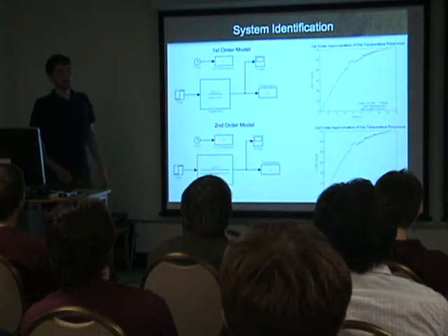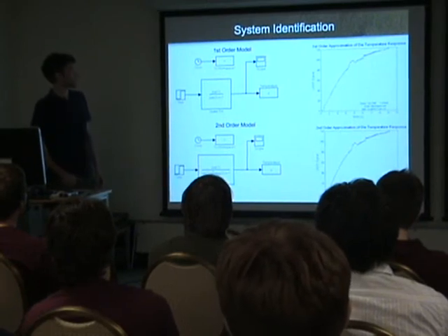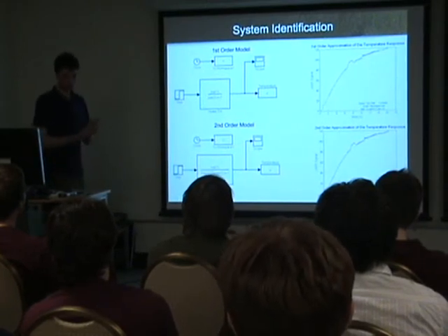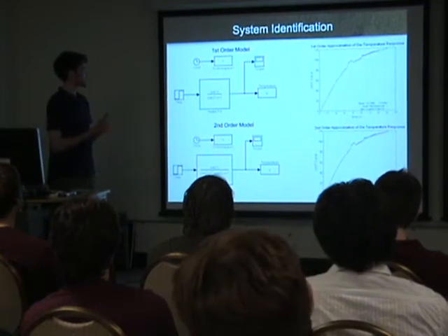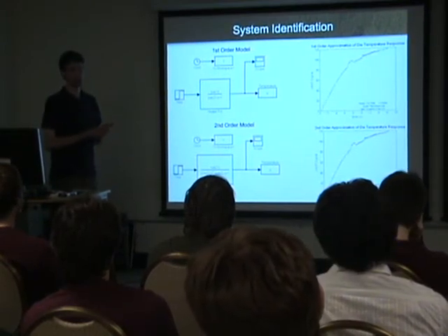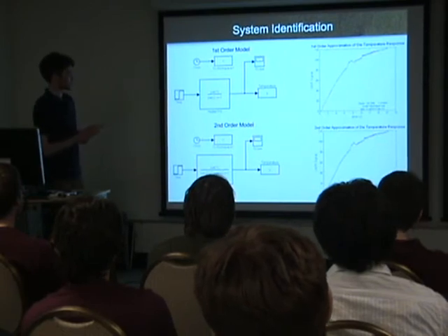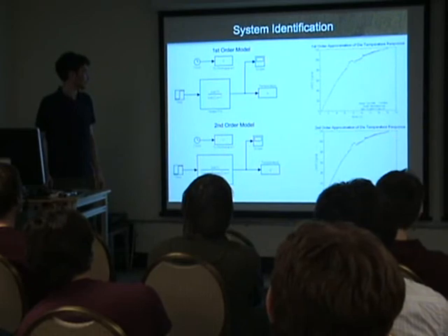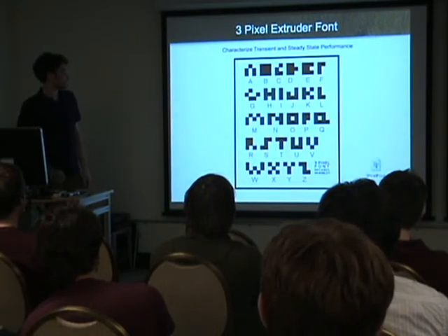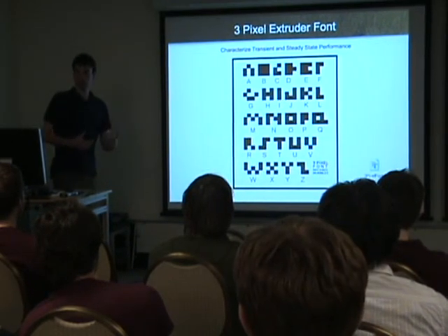But then we get into the fun stuff. We do an initial system identification on my die, so I could make a math model of it and simulate. This is a regression-based system identification technique. Pretty simple stuff, and fit first order, second order system to it, so I can get an accurate model later on. And then obviously we've got 3 heater pins.